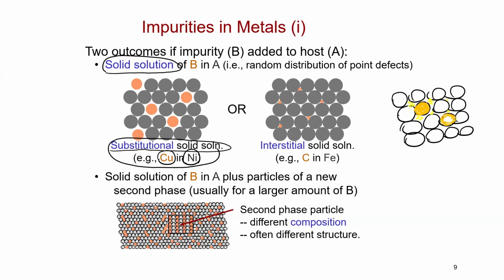So likewise, we call it substitutional. You don't have the nickel there, you have the other type, copper, here. But if you consider iron and carbon together, iron will stay like this, and carbon atoms are very small. They don't have to replace iron to stay inside.